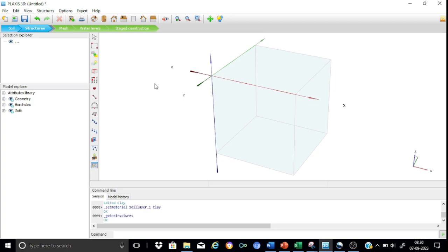For this, we will systematically follow a procedure. First, we shall develop a polyline, and for the polyline, we will develop the plate surface, and then we shall extrude this plate surface in order to develop a 1/4 circle cylinder, and then we shall remove the surfaces, explore the surfaces like that. So let us first proceed to the development of the plate using the polycurve option.